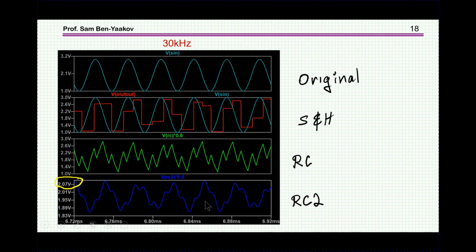So what's the conclusion here? Well, there are many ways to go, and you can do it in a simple way. You can do it by ripple cancellation. You can do it by sample and hold. It would appear, though, that simple filters, first order, second order, maybe a more sophisticated filter, like one with an inductor, so with a complex second order transfer function, could actually be better.